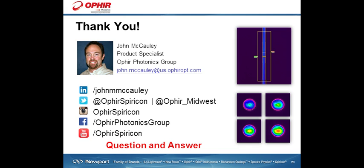Same thing with beam sizes. You're going to see the same thing in beam sizes. If you've got a cracked output coupler or damaged optics, you're going to see a beam size that's X, and you're going to see it grow like crazy. So this is really where the laser measurement products come into play: it gives you a better understanding of how your laser is performing over time.